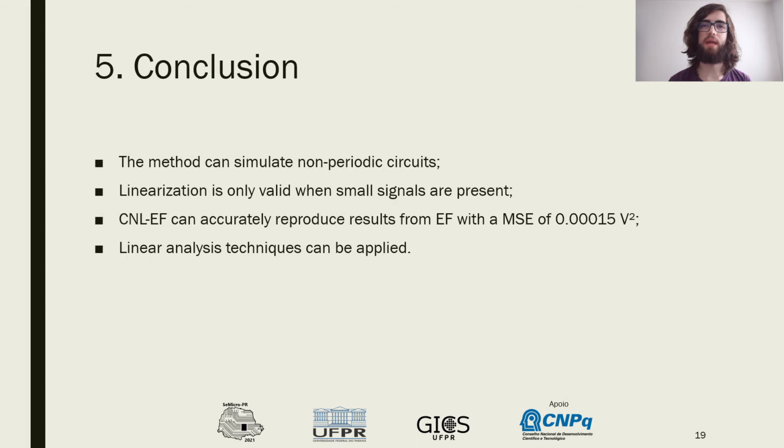The proposed method accomplished the set objective to simulate non-periodic circuit responses. By testing it under different conditions, it was shown how the linearization can only be applied in small signals. Also, CNL-EF can accurately reproduce results from other circuit analysis methods, such as EF, in the specified conditions with an MSE of 0.00015 volts squared, and with the benefit of being capable of applying linear analysis techniques.